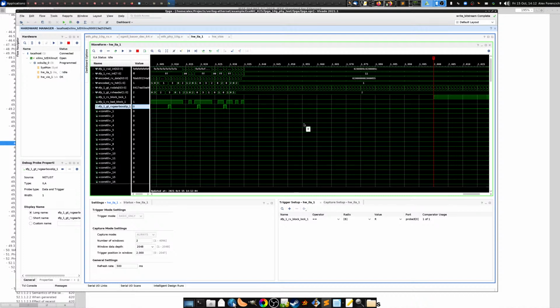You can do the same thing in fabric logic if you want with a gigantic barrel shifter that takes up a huge amount of logic resources, but it's easier and simpler just to request that the transceiver scoot over by 1 bit. Right, so that's the gearbox slip. So the trigger here is set on block lock. When block lock goes high, that's when the ILA is triggered.